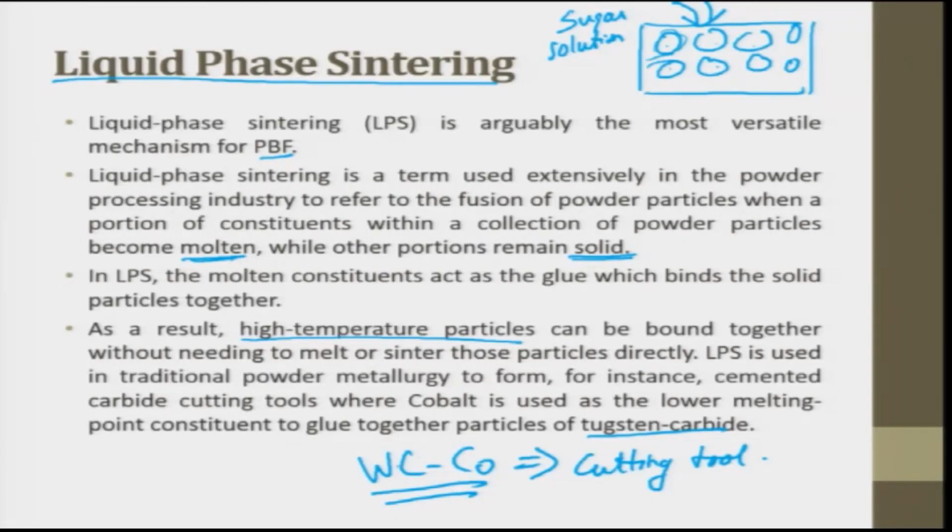You just mix whatever you want, tungsten carbide plus cobalt. The cobalt content is varied depending upon your requirements. With more and more cobalt, the product you make can take tougher and tougher loads. Once you reduce the cobalt content drastically down to 1%, 2%, it will be predominantly tungsten carbide. It can withstand very high thermal shocks, and it can take very high compressive loads.